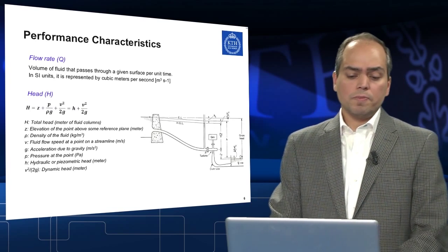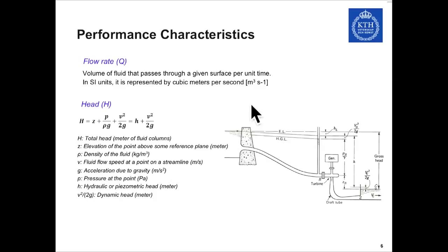Talking about the flow rate, then we come to the next parameter, which is the head. The available head, you could see that it's related to the Bernoulli equation, and then the level of the static head on the reservoir side and the available head on the turbine side. There are pressure losses along the system before water reaches the turbine.